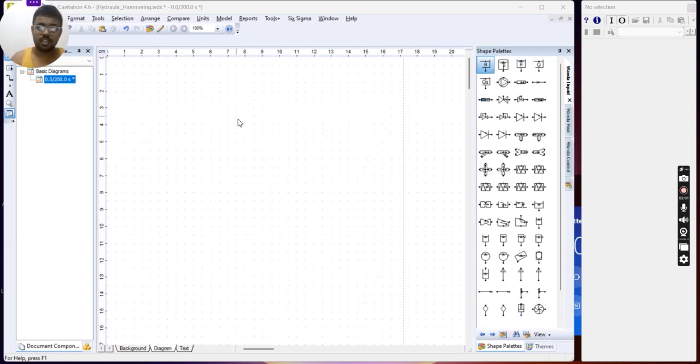During manufacturing there may be some cracks, and at the tip of the crack there may be a rise in stress due to these pressure transients. If this stress goes beyond the ultimate tensile strength, then there may be a sudden catastrophic failure, and that you need to avoid.